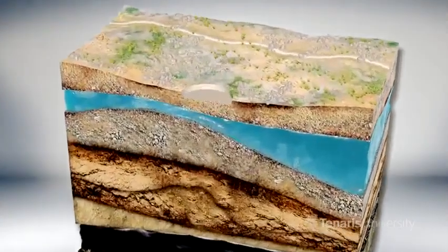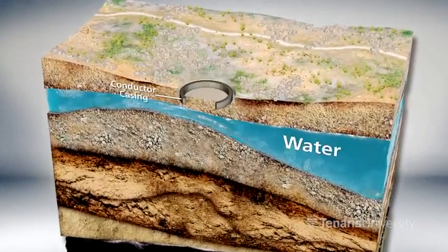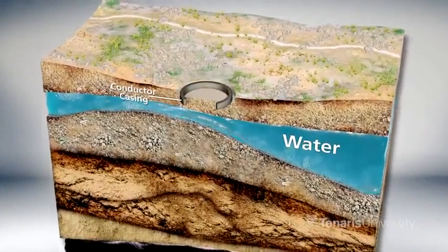We will start drilling our well, and the first casing to be run is the conductor. This is required to circulate the drilling fluid up to the surface without eroding the upper sediments below the rig foundations. Generally, this is a very short string, normally consisting of 1 to 3 joints, and as the loads at the surface are not severe, any pipe can eventually be used for this application. There is no need to make a specific design for it.